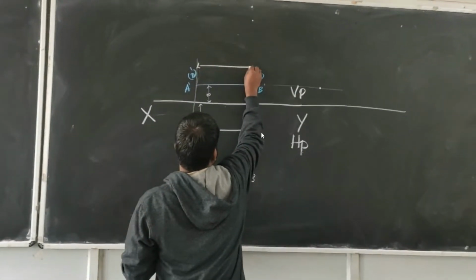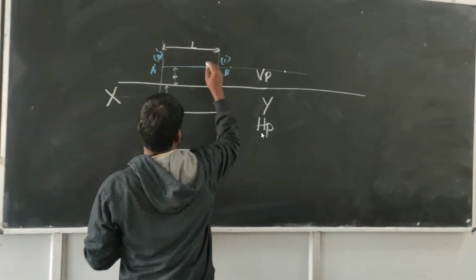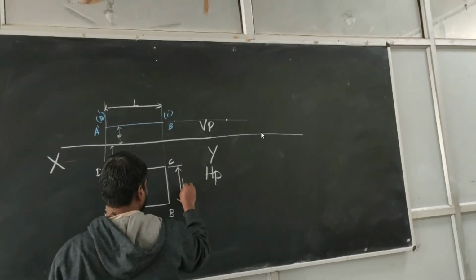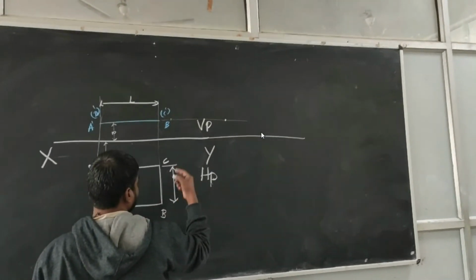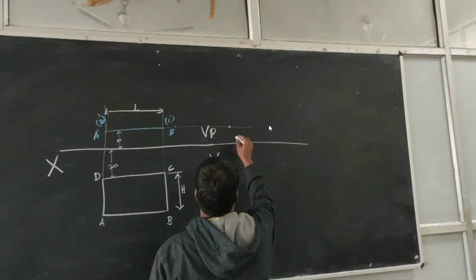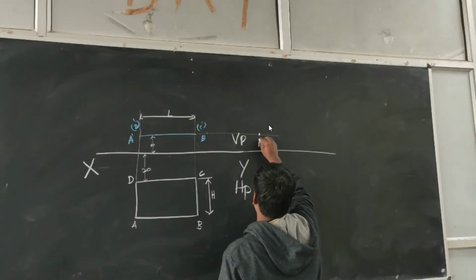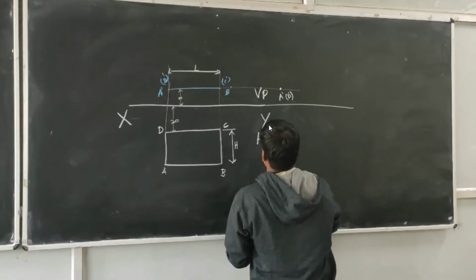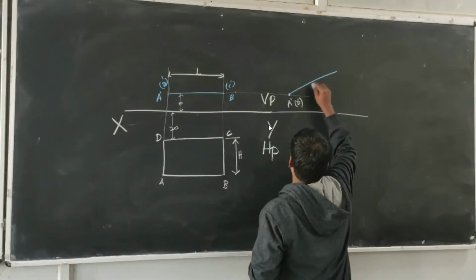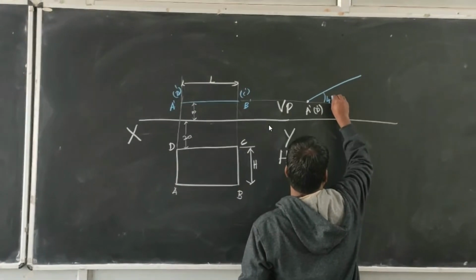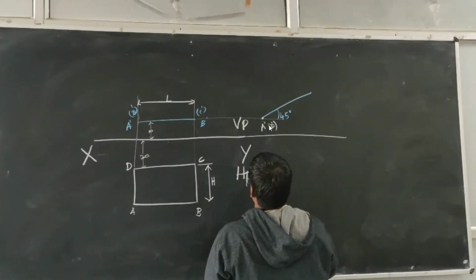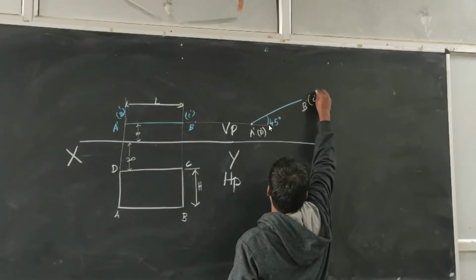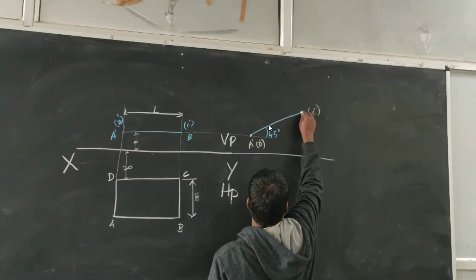So let us take that as the length. That length is easily available. That is the height I have shown. Let's put the height. The arrow marks you have to use properly. Then, as I told you, the points A dash and D dash are going to make some angle of inclination. First you mark the angle. I am taking 45 degrees, which is an easy way to identify and show the angle of inclination. Up to that length I know, then mark B dash, C dash.